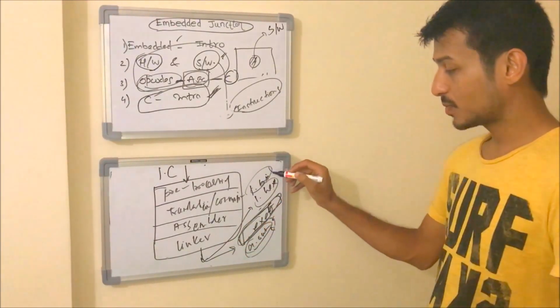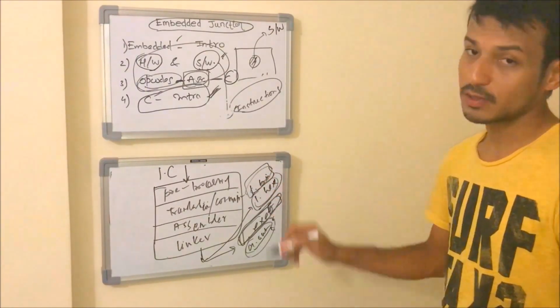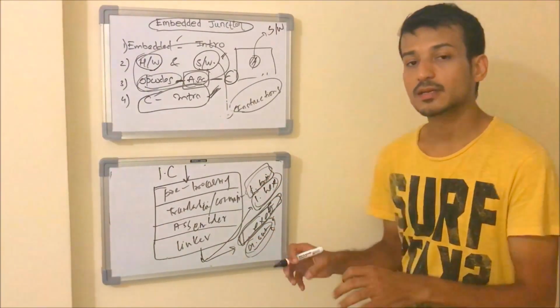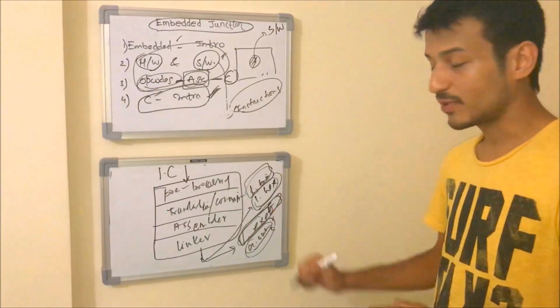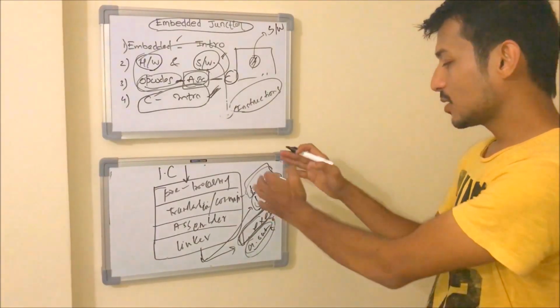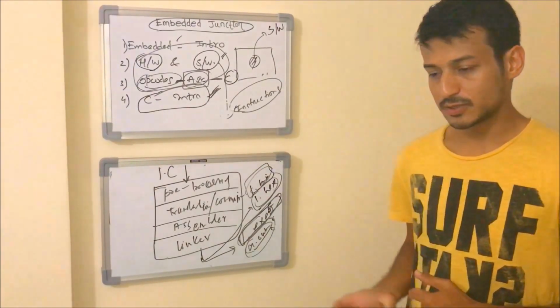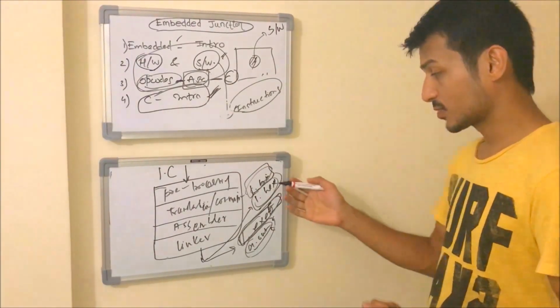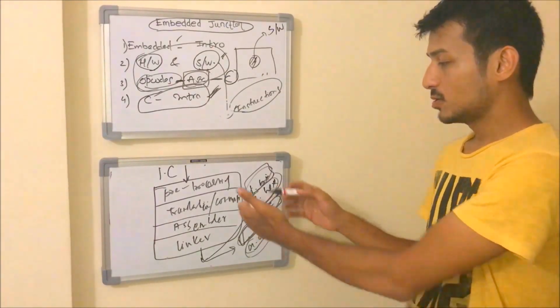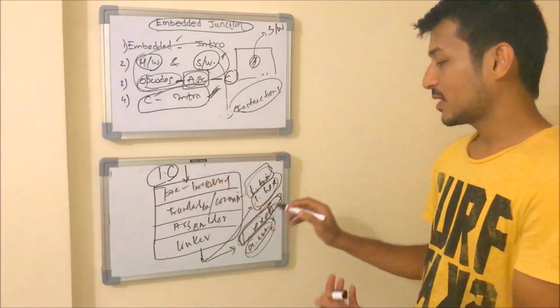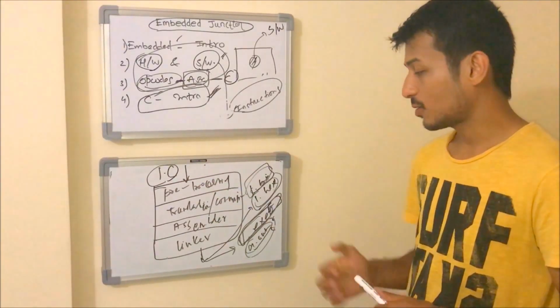That information is not present in one.binary or one.hex. So in general, all of these files have the opcodes of the microprocessor loaded, and using the compiler, we can convert a C file into a hex file or binary file.